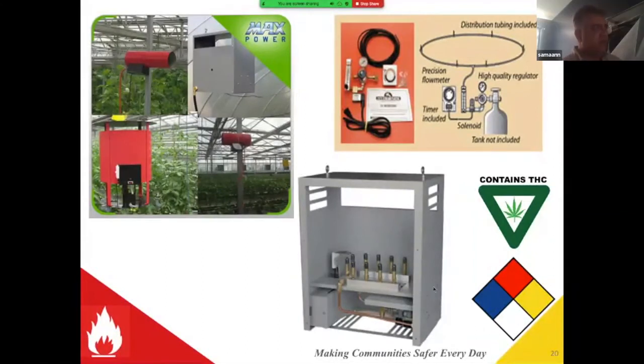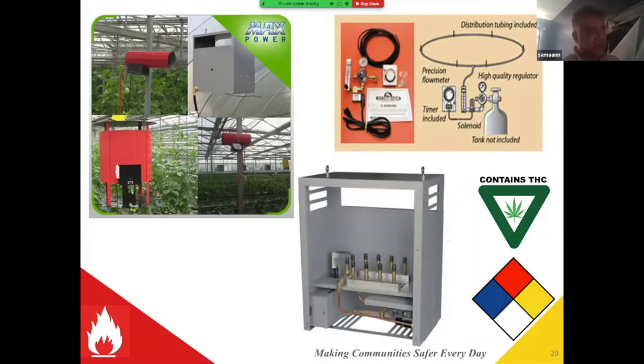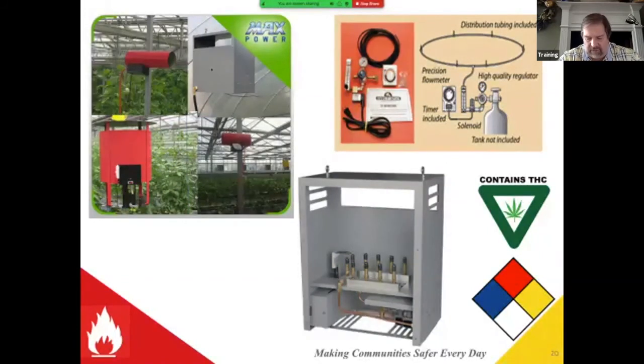Well, I just wanted to say one more thing. When you go to the same IFC section 621.1, it talks about it has to be tested and listed to ANSI Z21.11.2, and it's supposed to have oxygen depletion sensors on those. Does that 621 apply to that other section in 5? Most definitely. Okay. Yep, you're right. And the unlisted ones will not have those depletion sensors normally, the ones I've seen.